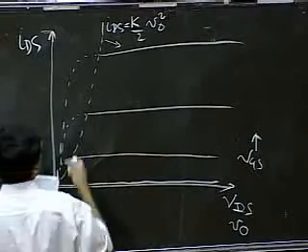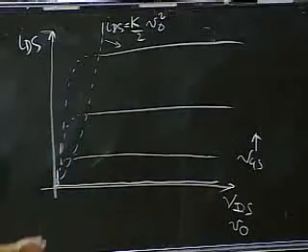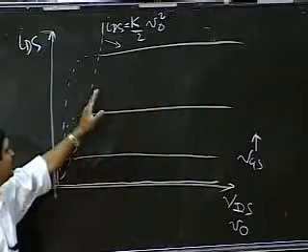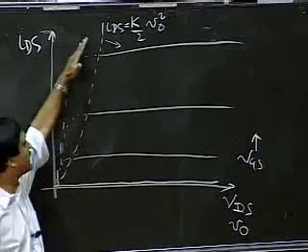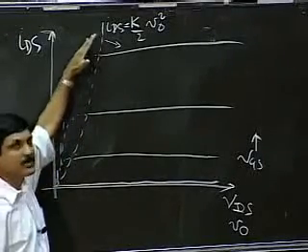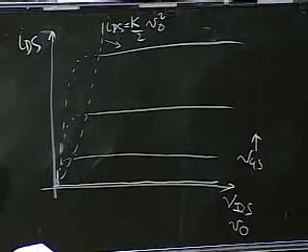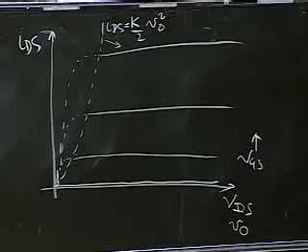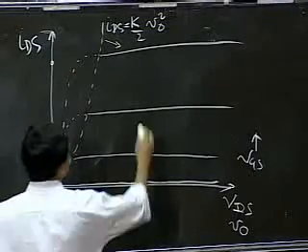Just that we focus on the right-hand side because that's where the MOSFET is in saturation, and on this side, the MOSFET is in its triode region, and we discipline ourselves not to operate the MOSFET such that it's in its triode region. Okay, so those were the device characteristics, and then I could plot my load line equation.